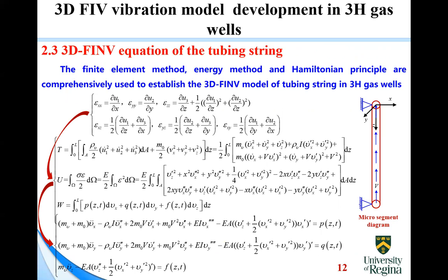Once we know the temperature and pressure in the wellbore, next I will introduce the three-dimensional flow-induced vibration equation of the tubing string. The finite element method, energy method, and Hamilton's principle are comprehensively used to establish the three-dimensional flow-induced vibration model of the tubing string in high-yield gas wells.